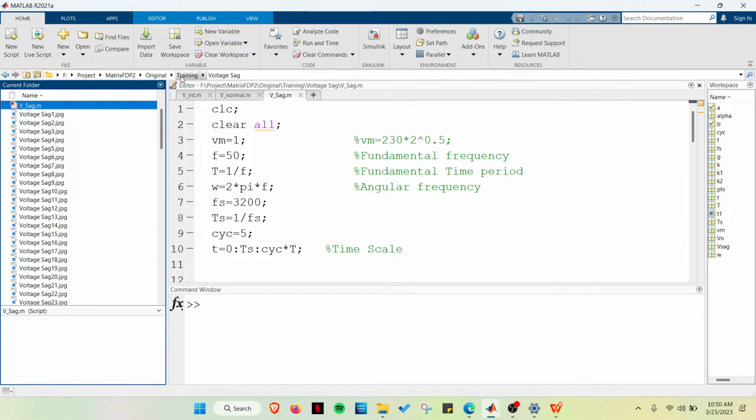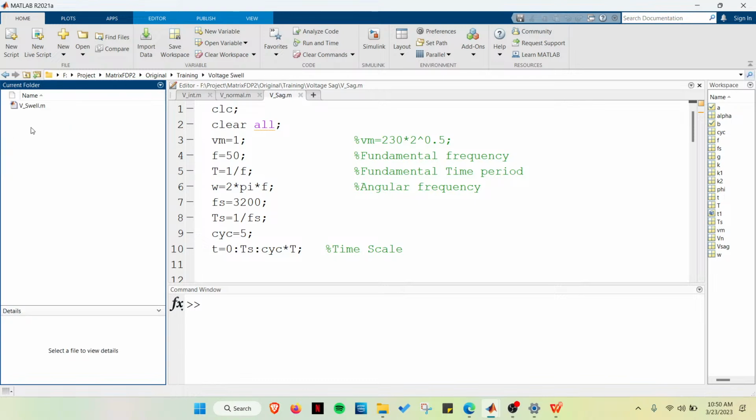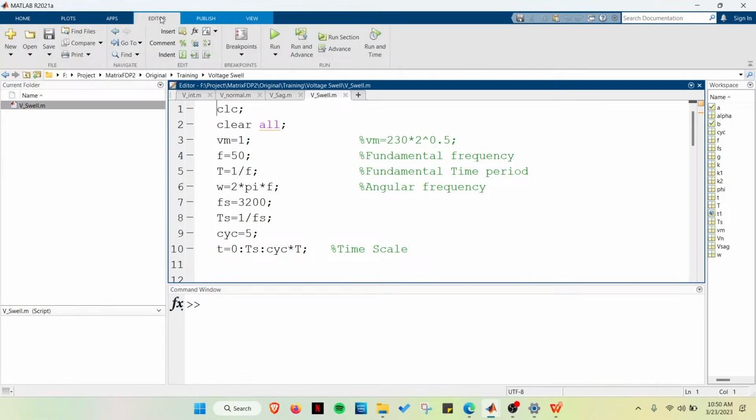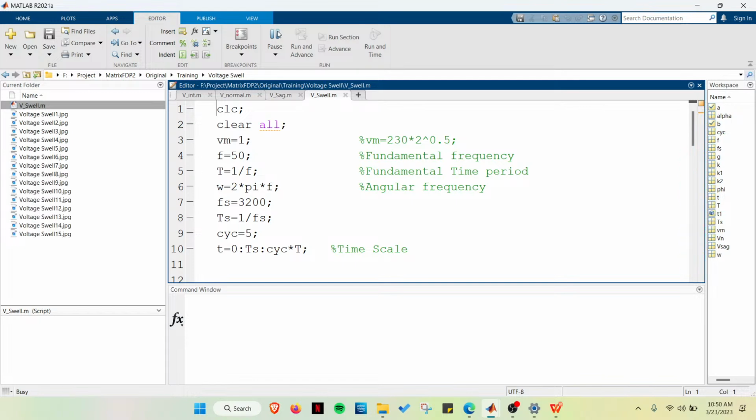Classification, only classification. Harmonic distortion is classified. It is just doing the classification of what kind of power quality issue is in the system. So just after taking the image, it will classify whether it is voltage sag, or harmonics, or interharmonics, or oscillatory transient, whatever is there. So then we can classify. Accordingly, the person can take the decision.